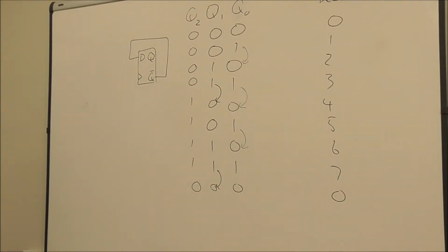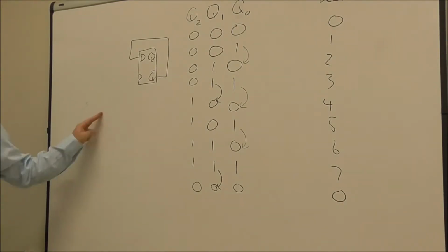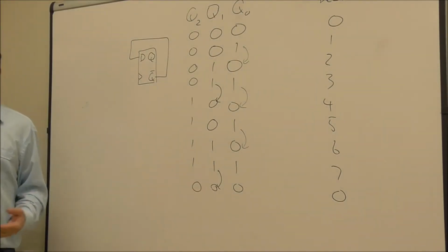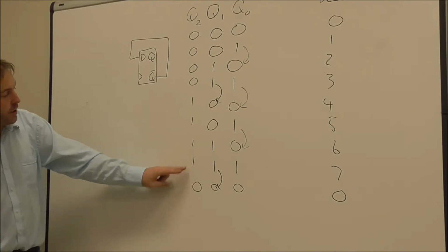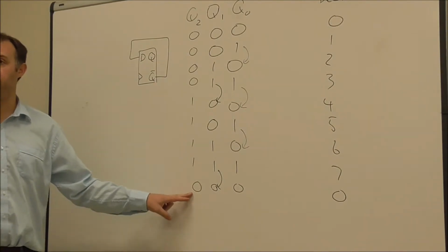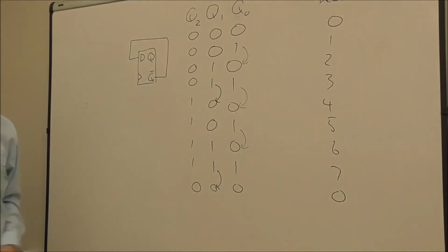Okay? So in the same kind of way, this is like an old analog clock, but instead of having 1 to 12 on it, it's got 0 to 7 on it. When you get to 7, you keep going back round, back to 0 again. Okay? And so it's like a clock. It's called modular arithmetic. It goes round and around and around. Okay? And so once I finish here, if I don't have any more bits to change, I go back to my starting value. And so this is counting up. If I keep going down, it's going to be counting up.